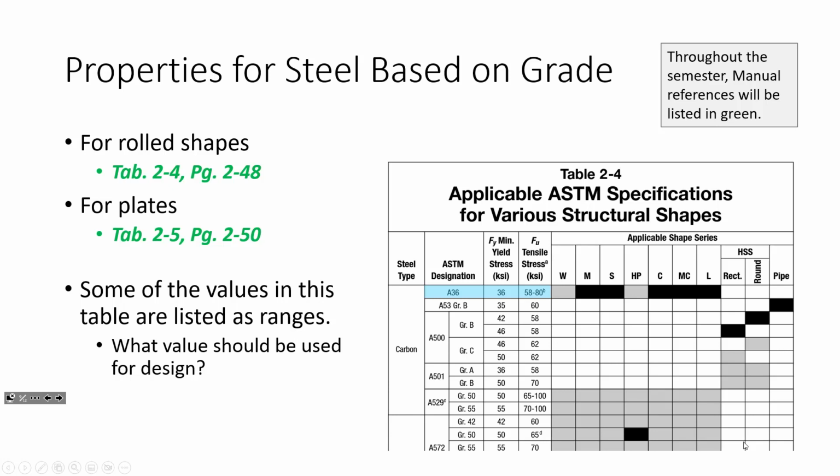It exceeds it, guaranteed. But from a design standpoint, you take the worst case scenario. What happened during the Northridge earthquake? After the Northridge earthquake happened, they did a lot of structural investigations, and they found that a lot of steel frames that were not supposed to fail did. And one of the reasons why is because of this range. So the amount of ductility that we expected, we didn't quite get, okay?